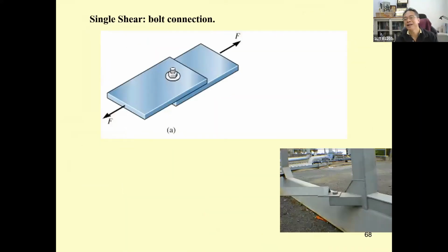There are a lot of things about this. This is going to be a single bolt connection. Where is my bolt? Sorry, it's down here. If you push this one like this, this one is going to be single shear. There are examples of single shear over here. There are only two plates connected to each other by the bolt. The eccentricity of the force is very small.